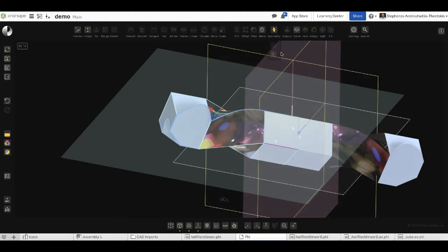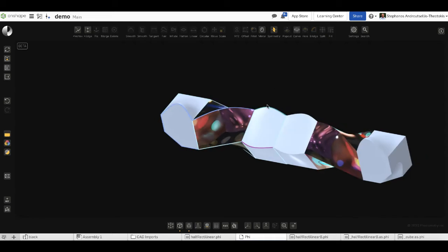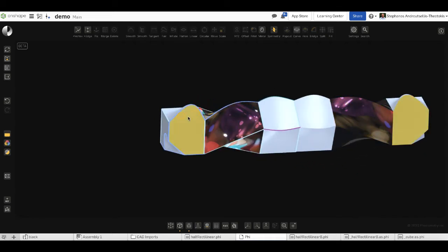And now only these edges that have been added, let me hide all of that, behave symmetrically. So the rest of my body does not participate in the symmetry. It does participate in the mirroring, but these specific parts of the body that I selected are additionally also parts of a symmetric manipulation. So I can have a combination of the two for more global or more local manipulations.